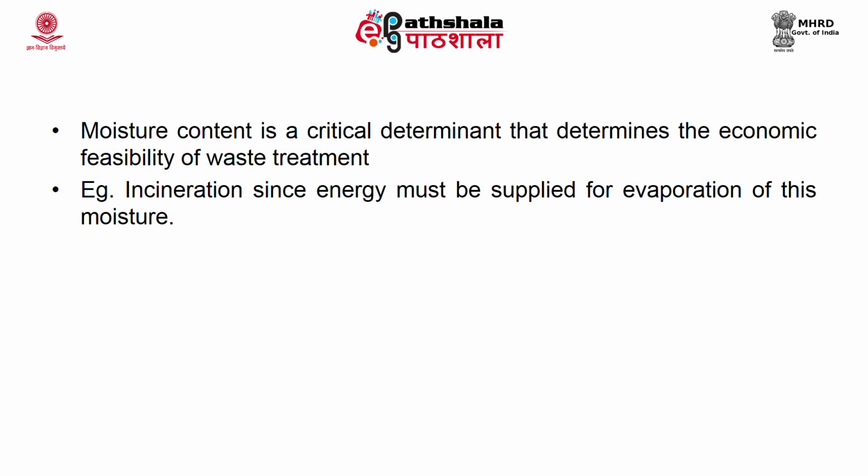It is very essential to determine the moisture content of a waste. This will help us determine the economic feasibility of waste treatment. For example, when applying incineration to a particular waste, it will help us determine the amount of heat that has to be given to an incinerator. That will help us understand the amount of heat required for evaporating the water or moisture present in the waste.